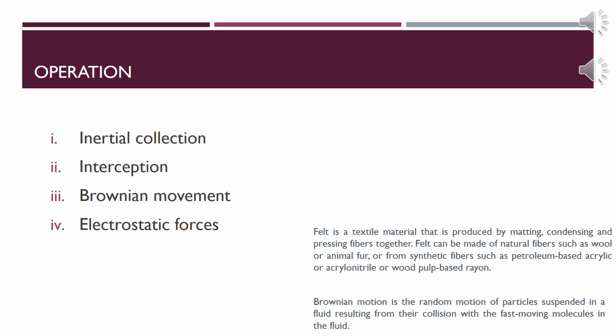Most baghouses use long cylindrical bags or tubes made of woven or felted fabric as a filter medium. For applications where there is relatively low dust loading and gas temperatures are almost 121 degrees Celsius or less, pleated, non-woven cartridges are sometimes used as filtering media instead of bags.